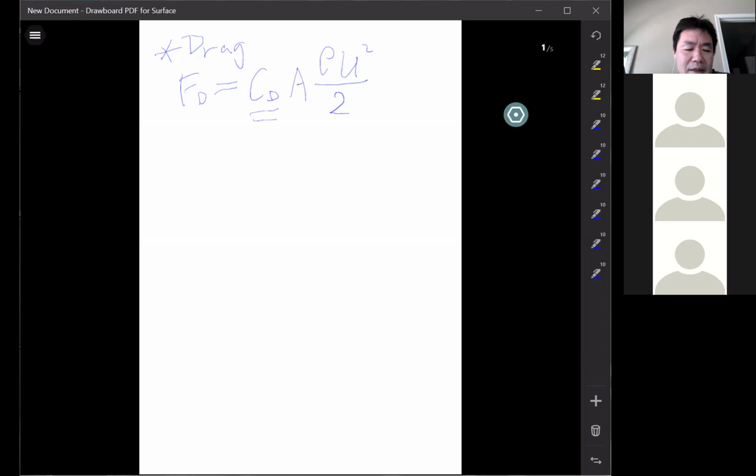Okay. Now these are two plots. I want to send you 6.10 and 6.9. This is for the drag coefficient for the cylinder and for the sphere. Sphere is 6.10. Cylinder is 6.9. So take a look at these two plots. The vertical axis is CD, the drag coefficient. The bottom axis here is the Reynolds number. So you need to know the Reynolds number in order to find the drag coefficient from the plot, right? So what is the Reynolds number? Anybody remember?